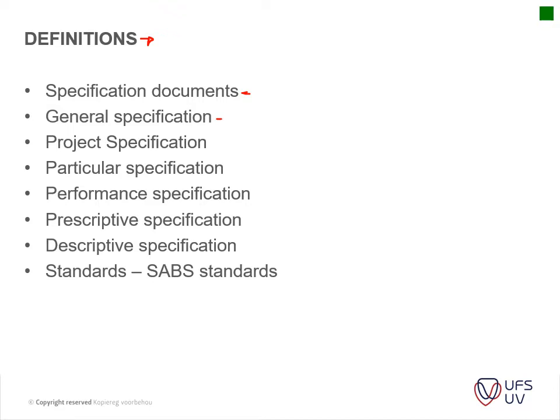Should it be tested at 7 days, 21 days? What is a set of concrete test cubes? Is it only one test cube, or a set of 3 cubes? One is usually tested at 7 days, the other at 21 days, and a third is left as a supplementary test if either of the first 2 fails.